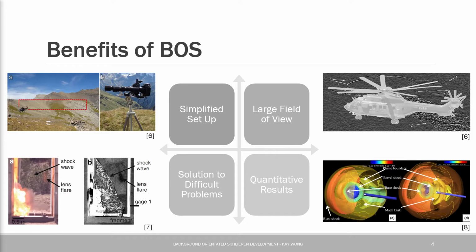Experiments take advantage of the ability to capture large atypical objects, the simplified setup, and the potential to extend analysis to not only flow visualization, but also quantitative measurements of density, pressure, and temperature. The German Aerospace Centre has visualized helicopter tip vortices and blade interaction using mountain terrain background, and even shockwaves from explosive and transonic wind tunnel tests have been achieved.